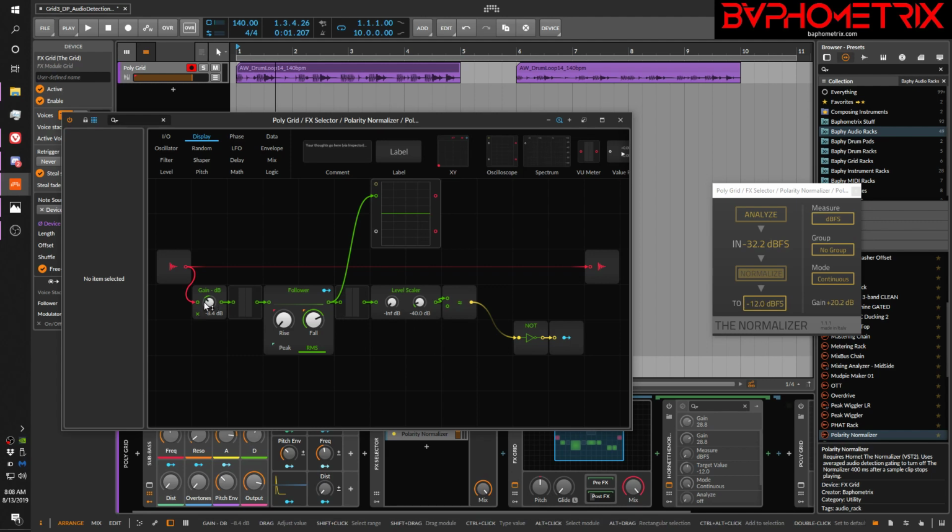So you have to play with the difference between gain. Like the drum signal here is super loud, so I turn down the gain because at 0 it's just peaking up this meter and then keeping this one super high too because it's just so much signal. So sometimes you need to adjust your gain to keep your input close to 0, peaking close to the top, but not at the top or over the top. And then you adjust your fall time to determine how smoothly and consistently the average envelope signal stays well above the 0 line.